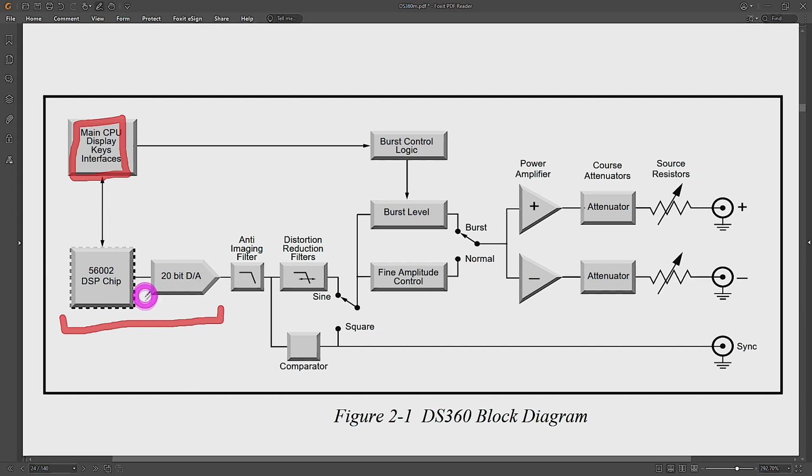Well, if I store all the parameters, all the data points in the digital domain in some memory, I can then feed it into a D2A converter on some very precise clocking, and then the D2A will create a sinusoid for me. And if I want to change the frequency of that sinusoid, I don't necessarily need to resynthesize everything. I will just change the phase accumulator functions and the way that data is fed into the D2A. So the concept of DDS is now really well established, and there are many clever ways to do this. But this combination has several advantages because you can get really nice and low jitter. And importantly, your D2A will need to run at a fixed clock frequency, and just the way you feed the data would have to change.